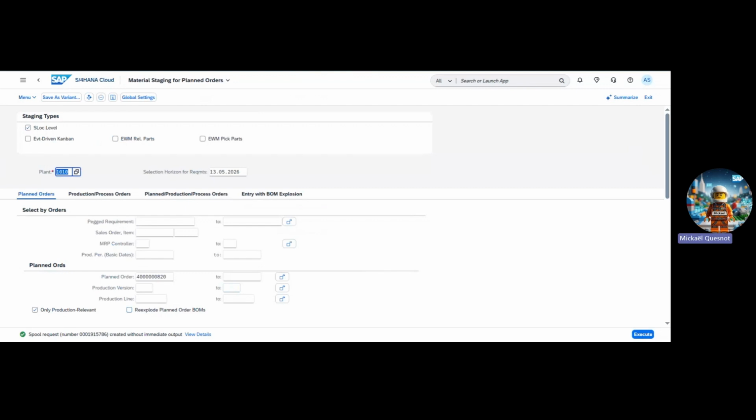Missing material is transferred to the shop floor for the designated storage area. Right now, confirm repetitive manufacturing, inclusive of backflush of material. This activity executes multiple activities in a single step, such as finished product goods receipt, backflush of component material, posting of cost to the cost collector, and creation of material and journal entry. So let's start. Confirm repetitive manufacturing.